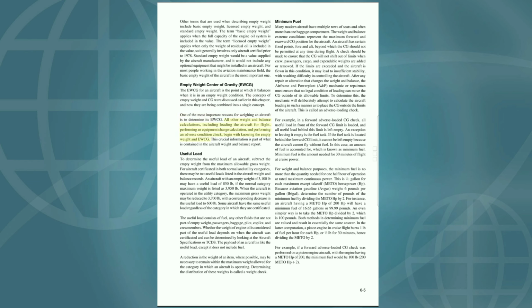All other weight and balance calculations, including loading the aircraft for flight, performing an equipment change calculation, and performing an adverse condition check, begin with knowing the empty weight and EWCG. This crucial information is part of what is contained in the aircraft weight and balance report.